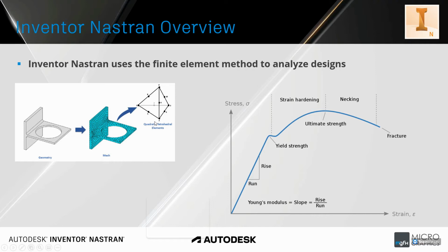There's a couple of ways of drawing this. In 3D, you generally get quadratic tetrahedral elements. When you're doing this kind of finite element analysis by hand, which is very tedious, you'd find that you'll often have to work in 2D and work with basically segments of lines and that sort of thing.